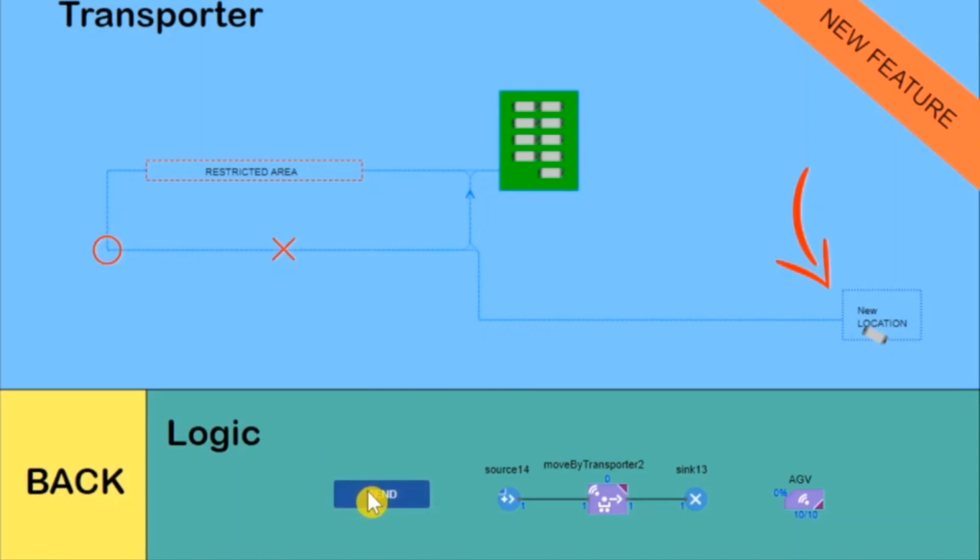We can specify a restricted area by drawing a polygonal node, and you can customize the access to the node and the speed of movement through the node for transporters with free space navigation and path guided navigation. Speed restriction and access restriction do not depend on each other and can be specified separately. Nodes with different restrictions can overlap each other. In this model, the restricted area only allows 1 transporter to go in at a time.